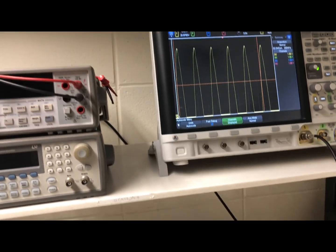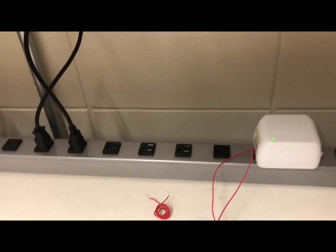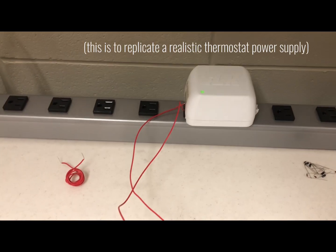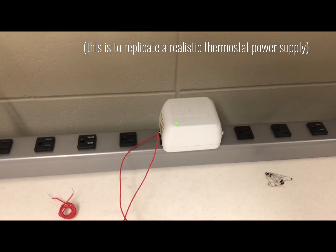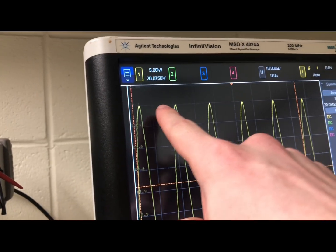Hi, I'm Andrew Freeman with the power subsystem for the Smart Vent Thermostat. So the first major part of this subsystem is actually powering the main hub. And right here we have a 120 volt AC to 24 volt AC converter. And just to show you, right over here, we've got this hooked up to the oscilloscope. We've got an output of about 36 volts.